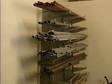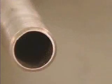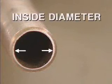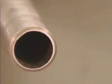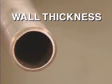Pipe sizes are generally given in terms of a dimension called nominal pipe size. For pipes from 1/8 of an inch to 12 inches, nominal pipe size is the approximate size of the distance from one inside edge of a pipe to the other inside edge, or the inside diameter. An approximate inside diameter is used to assign nominal pipe size because the actual inside diameter will vary based on the wall thickness of the pipe.